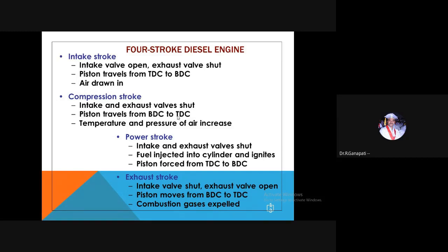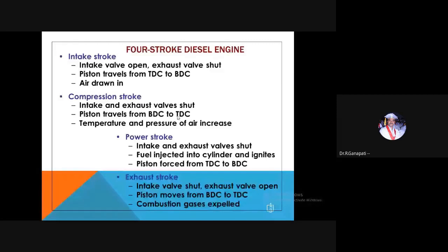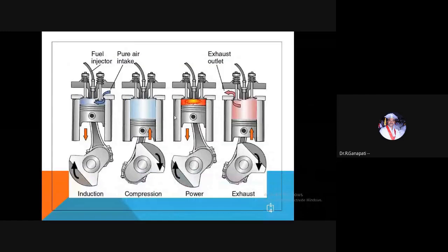And the final one is the exhaust one. At the time, the inlet valve will be closed and the exhaust valve will be open. And the combustion products inside the engine cylinder rush to the atmosphere through the exhaust manifold via the exhaust valve.